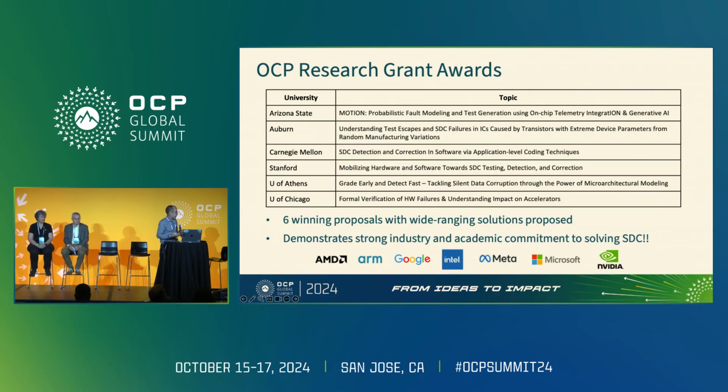to conduct research in the areas of SDCs, and the key to the long-term solution here is modeling, proper modeling, taking into account changes in the manufacturing process and in chip designs. Because really, there's a big difference between a bug and SDC. A bug is something that you designed in. SDC is just a collection of events that led to part of the chip malfunctioning. And even worse, malfunctioning in a silent manner that is really hard to detect.